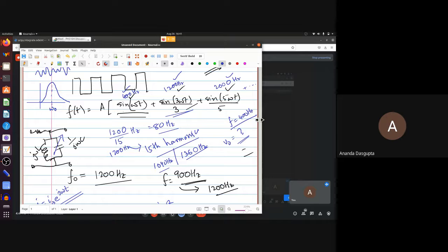There is a standard electromagnetic effect. And so for high frequencies, the inductor will actually behave like a rather large resistance also, on top of its impedance. So its behavior will change. So if you keep on changing the resonance frequency by changing the circuit, you will run the risk that your circuit will actually behave differently at different frequencies. It's much easier to control the source frequency rather than control this resonance frequency. It's just a matter of practical convenience, nothing else.